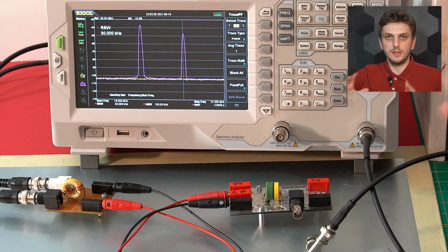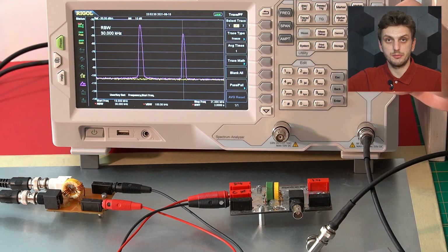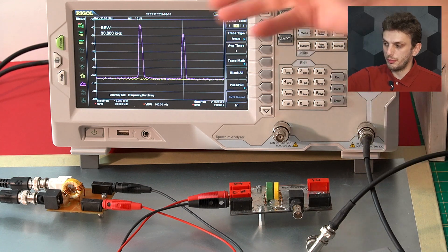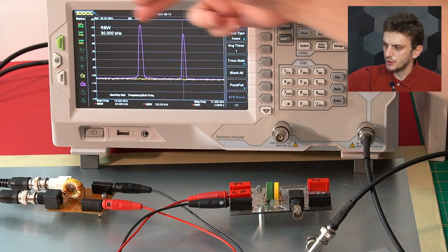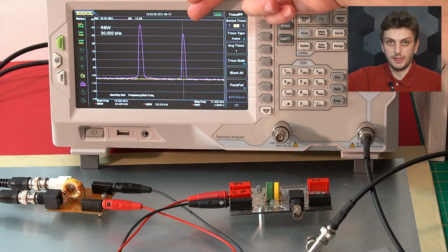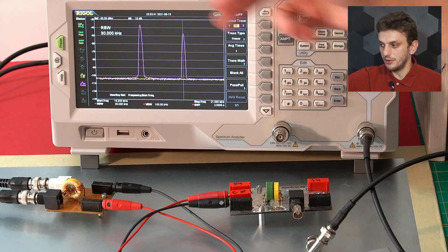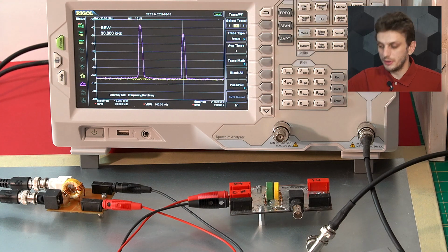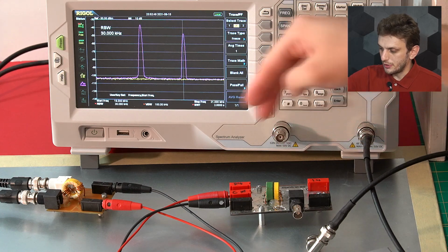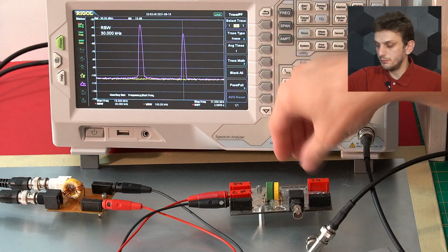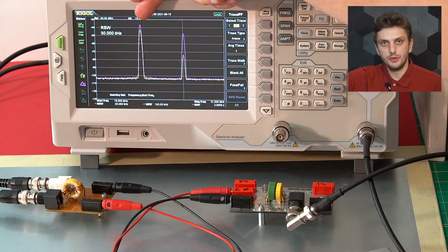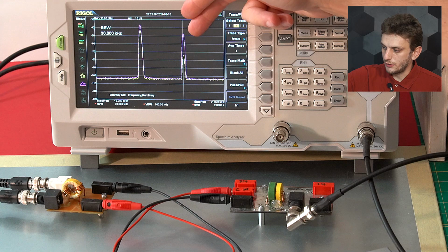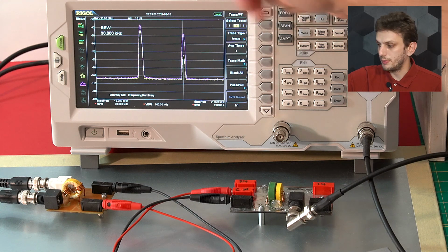Now, just to see how well this device works over a wider frequency range, I made the exact setup as before, but looking at two spikes, one at 19 MHz, one at 20 MHz. So I already prepared the measurement with the LISN, in which I have the two measurements in pink, so this is the unseparated measurement. And now if we connect our separator, first of all on the common mode input, we can see our common mode spike slightly attenuated, but we have a far greater attenuation on our differential mode spike.